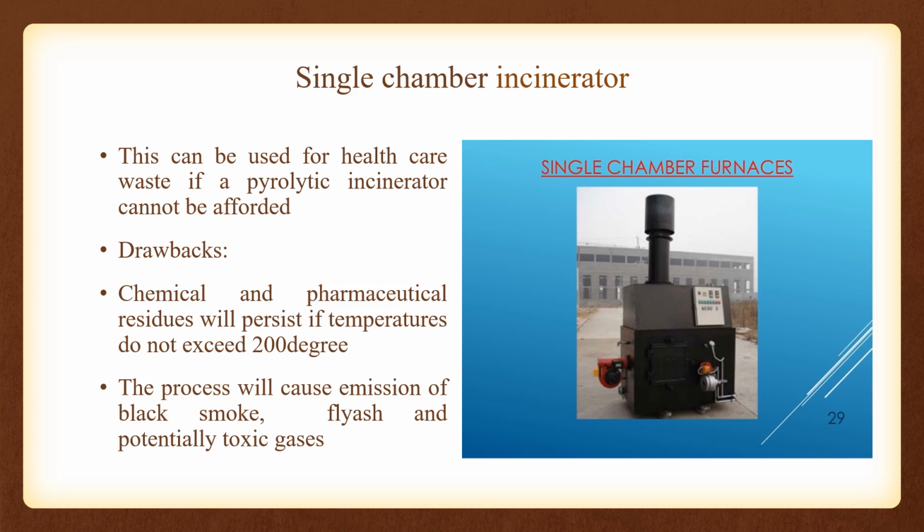What is the second one? That is the single chamber incinerator. This can be used for healthcare waste if a pyrolytic incinerator cannot be afforded. That is, if you can't afford it, you can go with a single chamber incinerator. This type of incinerator treats the waste in batches. Loading and de-ashing operations are performed manually. The combustion is initiated by addition of fuel and should then continue unaided.